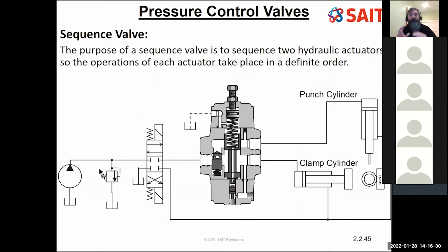I want a sequence of operations. I want one thing to happen at low pressure, allow the pressure to build up, so the next sequence of operations can occur. In hydraulics, there's a lot of pressure available, so I can have quite a few different items in my sequence. I talked about a 4-sequence operation earlier of moving the steel, clamping the steel, punching the information, cutting off the steel. You can do this with a bunch of sequence valves and hit go. Instead of having to have a really sophisticated operation that we would use today, we don't technically do this.